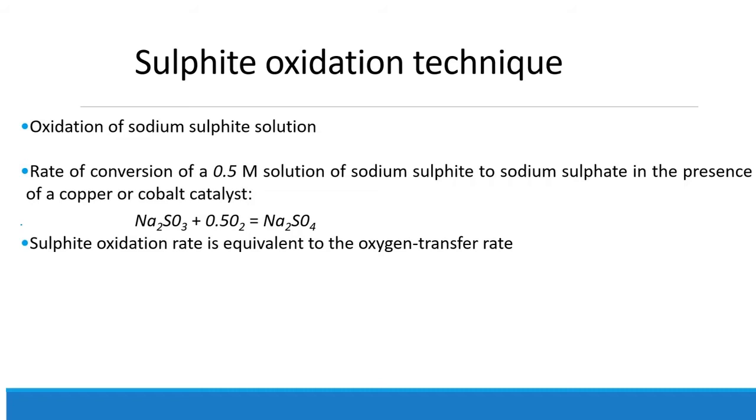The concentration of oxygen in the liquid bulk is zero. Thus, CAL is approximately equal to 0 and the system is a mass transfer controlled one. Hence, the measured rate of reaction is actually the mass transfer rate from which KLa can be calculated.